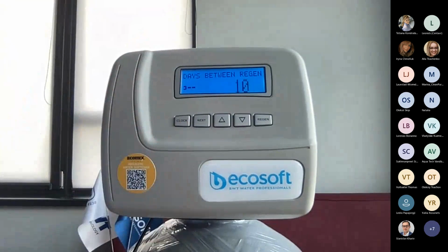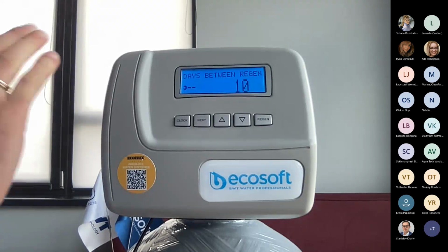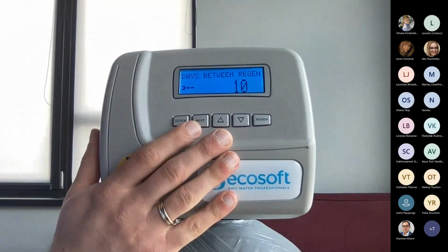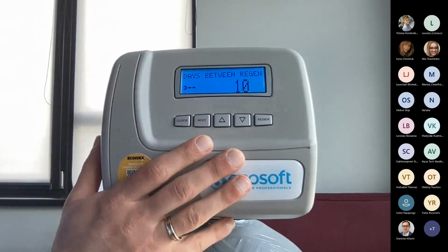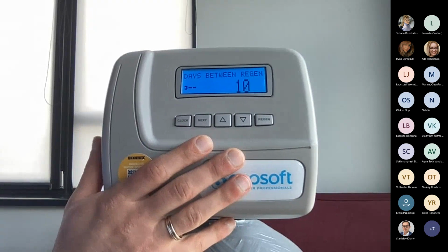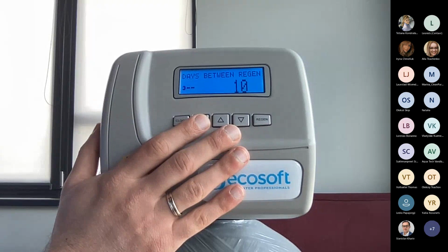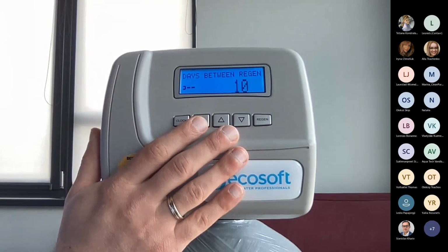Of course, if you are on a long vacation, like for a month, it means that if you keep the system as it is, it would hold 3 regenerations. So maybe you will deactivate it, but I would suggest not to do it and keep it as it is, because it's always better to consume some amount of salt rather than do the maintenance after the vacation period, especially when the iron content is very high.